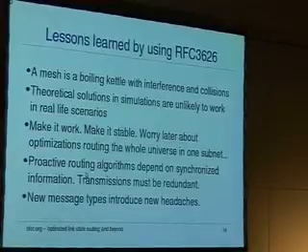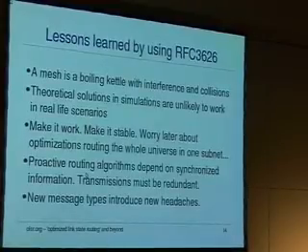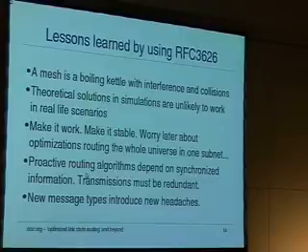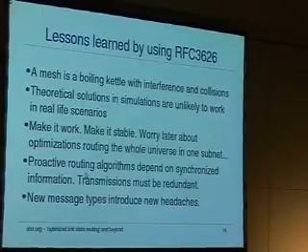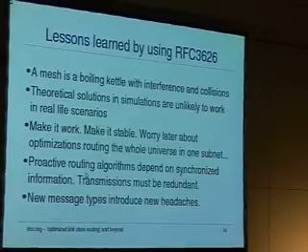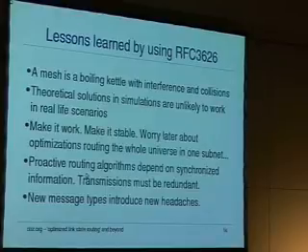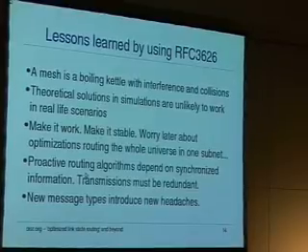and collisions, especially the mesh that we used because we had only one channel. We were transmitting on channel 10, so everybody is using the same resource, and there are lots of collisions. There are hidden nodes, exposed nodes. And if you need 10 dB signal-to-noise ratio to have a successful transmission with 2 megabit, well, a node that is far out of range still adds some 2 or 3 dBs noise to the noise floor you already have. So it cuts down the signal-to-noise ratio even if it is completely out of range.